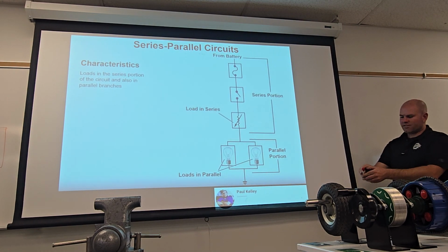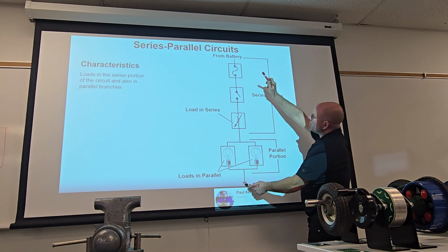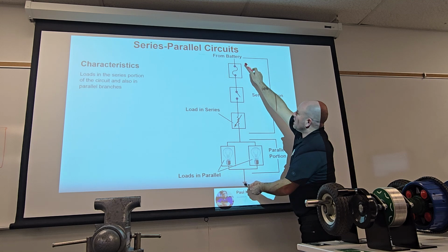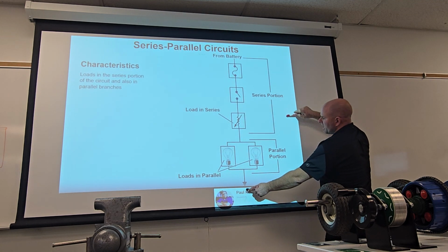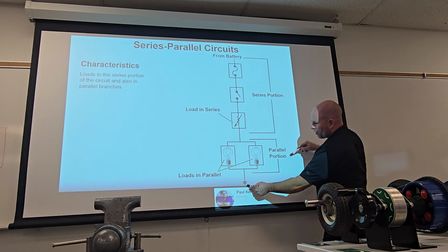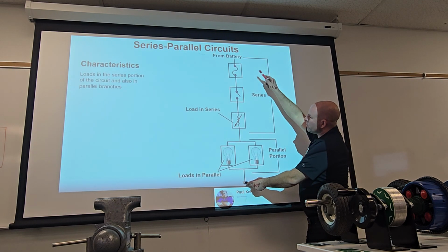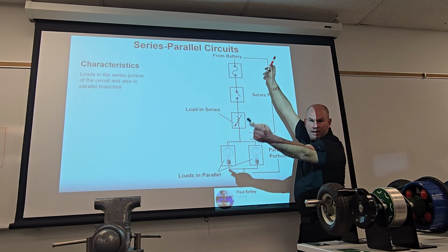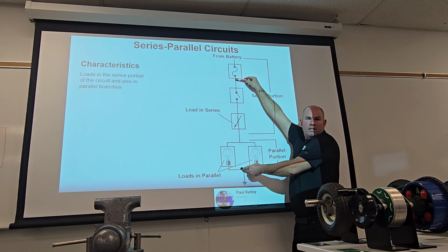I'm going to put my negative lead down here, available voltage, right? And then my red lead I'm going to put up here. If this was a computer up here, now you have another way for the electrons. They're going to go through your meter and go to ground. Make sense? So when we're doing available voltage, we're technically adding, you see my arms? I just added another circuit, didn't I? On available voltage, I did.